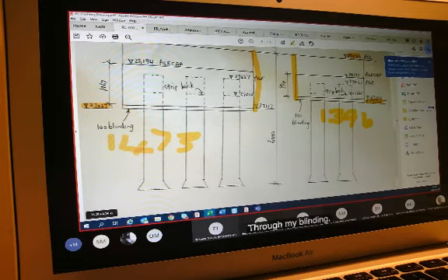Because that is the number of piles of type A that will protrude through my blinding. I then also have 2.13 by 0.91 by 0.1, and I then deduct 0.24 by 0.24 by 0.1 times pi times 4, because 4 is the number of piles for type B pile caps. Total.